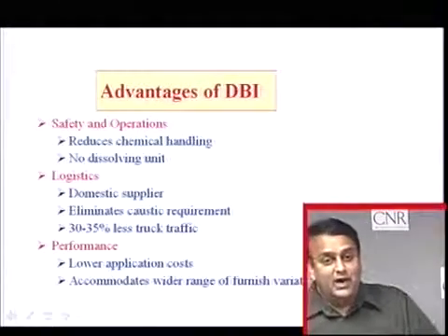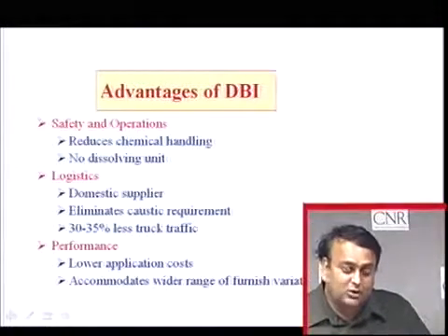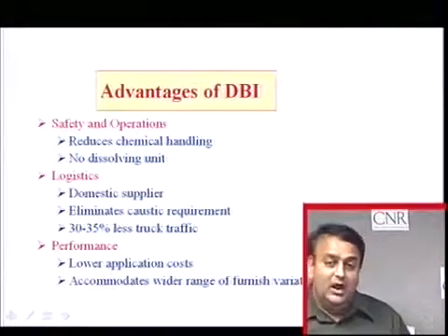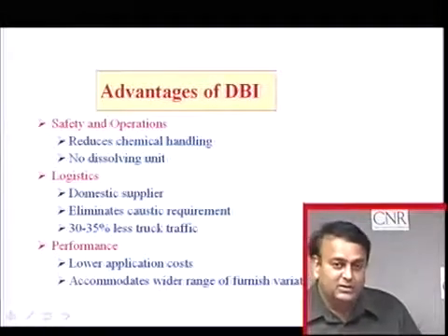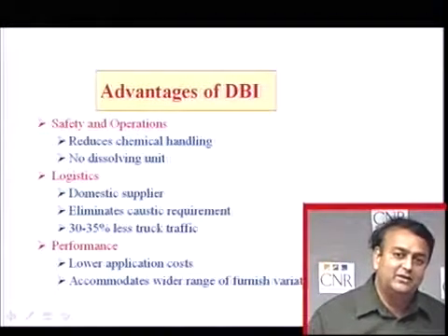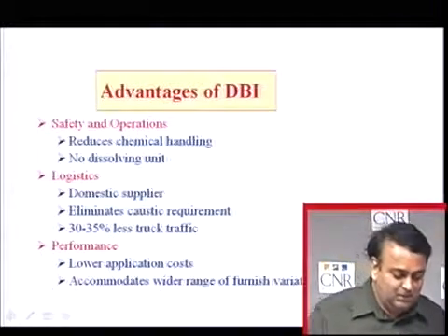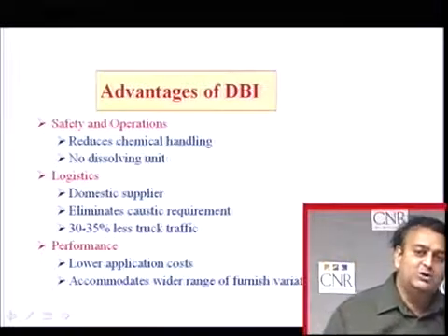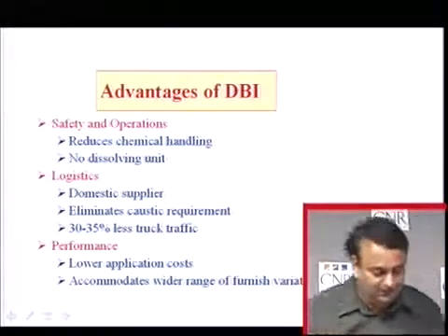Why do people use DBI compared to hydrosulfite or FAS? There are multiple reasons for that. First of all, both are stable liquids. You can put them in your mill and they can stay in your tank more than 5 years without degrading or decomposing. Whereas with liquid hydrosulfite, if you have a shutdown for more than 3 days, that liquid hydrosulfite can go bad in concentration. And you don't need a dissolving unit with the DBI. It's not a powder form, you don't need dissolving units, and there is no fire hazard associated with the DBI.